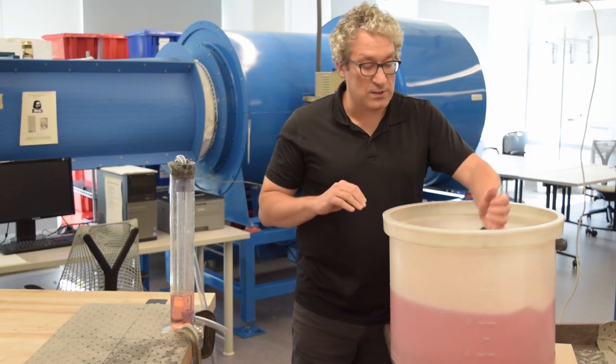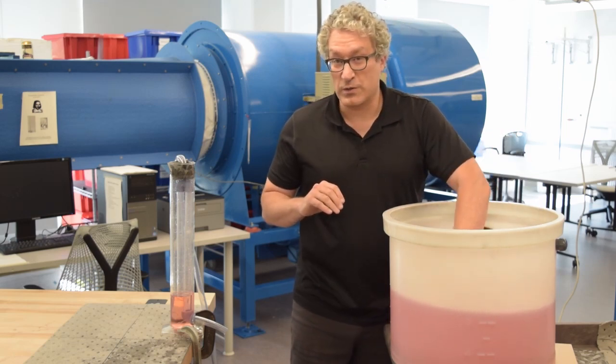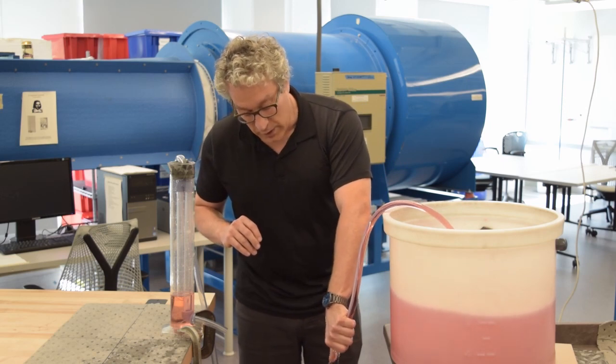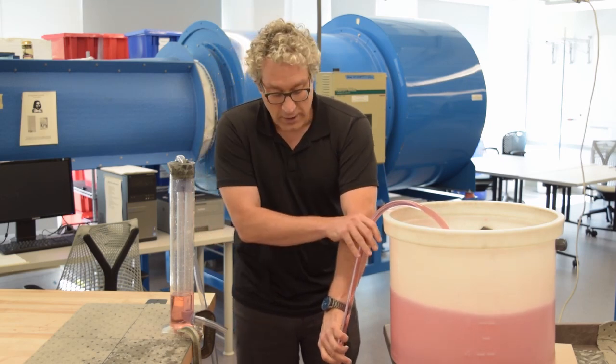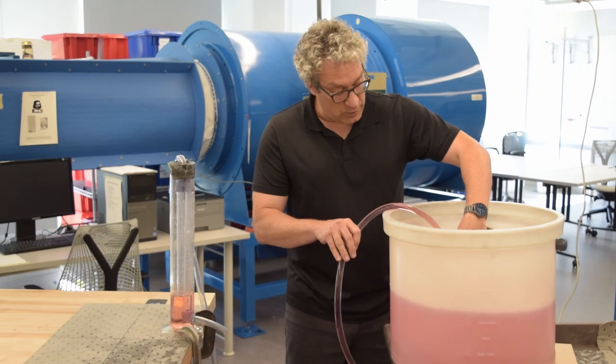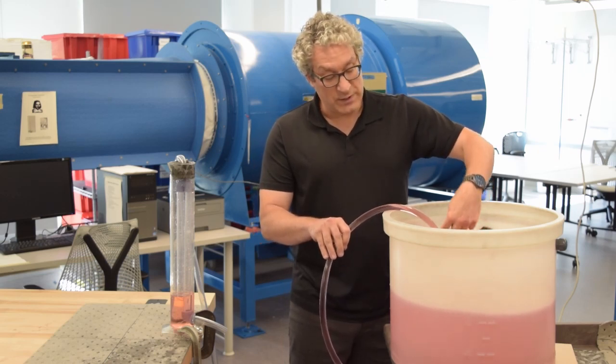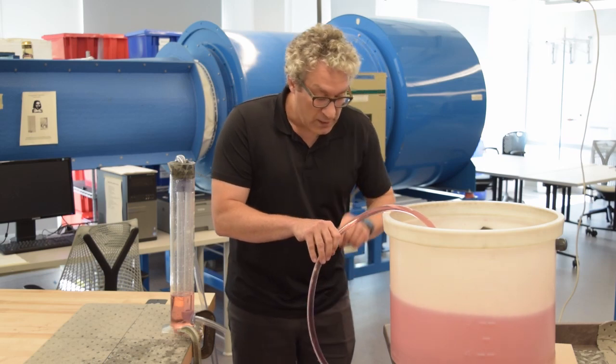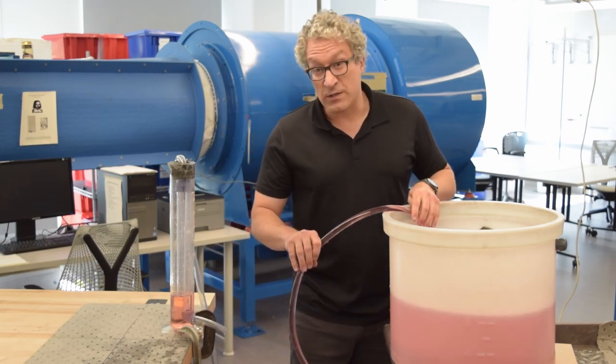Again, I take the same system, and I just dunk the tube in the water so that it fills with water. Now I can uniformly apply the hydrostatic equation with the density of water, and that predicts that the pressure first goes down, and then goes up. Now the hydrostatic equation doesn't say how fast this fluid moves.